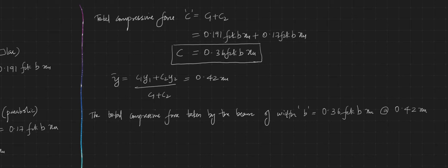Now our basic assumption in the analysis of a singly reinforced section was that the total tensile force is taken by the steel alone. That is, the reinforcement is taking the entire tensile force. So the total tensile force is equal to 0.87 fy, that is the stress in steel, into the area of steel, that is Ast, that is 0.87 fy Ast. That is the total tensile force acting on a singly reinforced section.